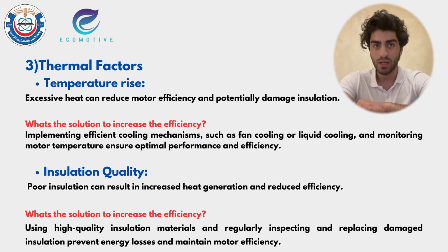Insulation quality. Poor insulation can result in increased heat generation and reduced efficiency. So we can fix that using high quality insulation materials and regularly inspecting and replacing damaged insulation. This will prevent energy losses and maintain motor efficiency.